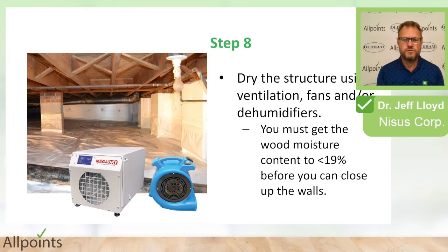dehumidification. If you don't have access to electricity, you need to think about chimney effect drying. So if you've got upstairs windows, open upstairs windows and downstairs windows, or a garage door, so you've got flow, ventilation through the structure to dry it out. Again, more ventilation is better. And if you've got battery operated fans, for example, that can also help you. Okay, but drying out the structure is very important, and you want to dry it out as quickly as you're able to do.